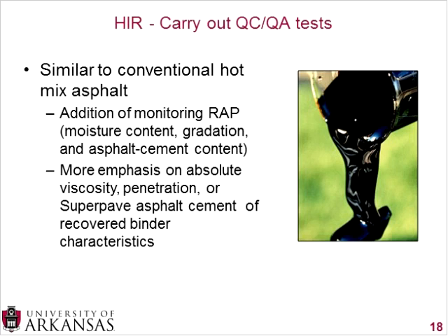And then also, what is the asphalt cement content? So all of these need to be monitored as you are going along the road. However, there is more emphasis on things like absolute viscosity, penetration, or the Superpave asphalt cement characteristics of the recovered binder. And this is because at the end of the day, since you're using all this in-place material, you want to make sure that they properly bind together.